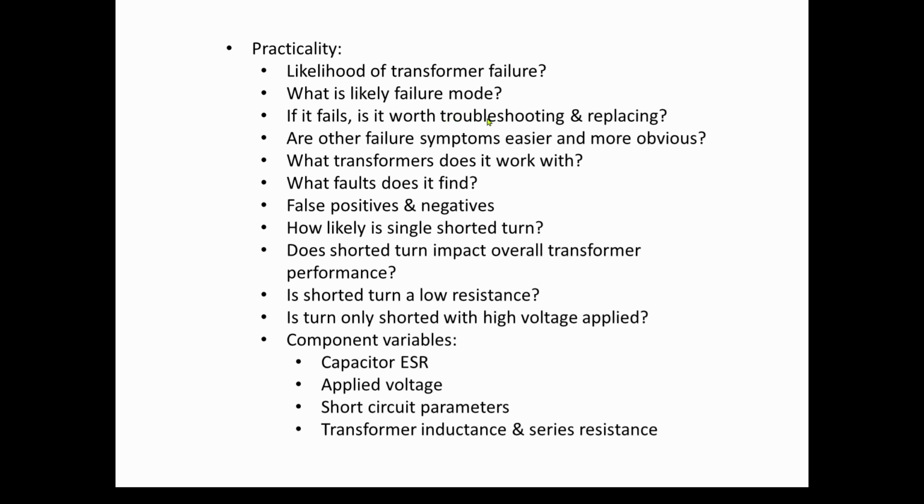Now, you may be someone who's got a box of switching transformers and you want to check to see which ones are good and bad. That's fine. But for most people, I think, is it really worth troubleshooting and replacing? The answer may be no. And are other failure symptoms easier and more obvious to detect, right? If you have a spike of voltage that destroys the insulation of the transformer, maybe the output is 0 and you don't need a ring tester. There are more obvious symptoms that you're dealing with.